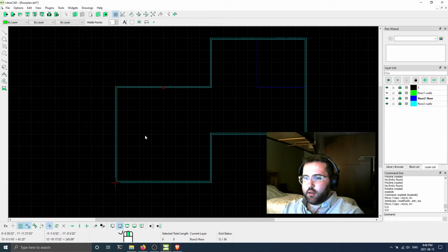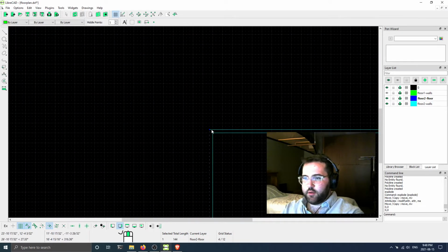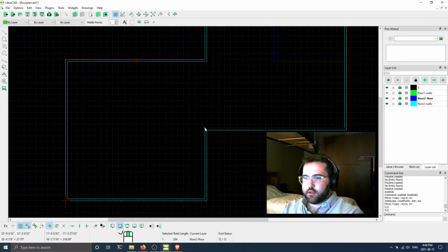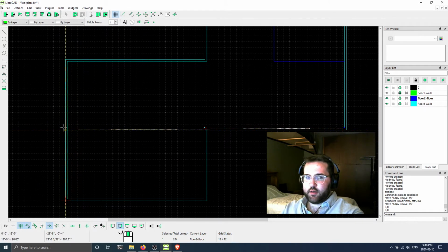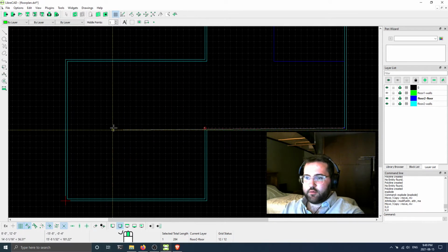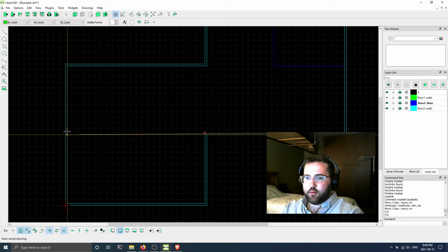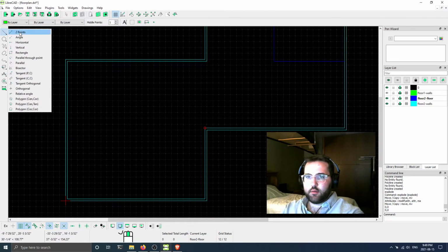And I think I'll turn this into a bedroom perhaps. So actually I'm going to end up undoing what I did before, but that's alright. I can drag this across. So now you can see that this isn't really lining up with anywhere on the grid per se. So what I might want to do is snap intersection. So if I was to now drag this, let's do this a different way. Let me just draw a line.